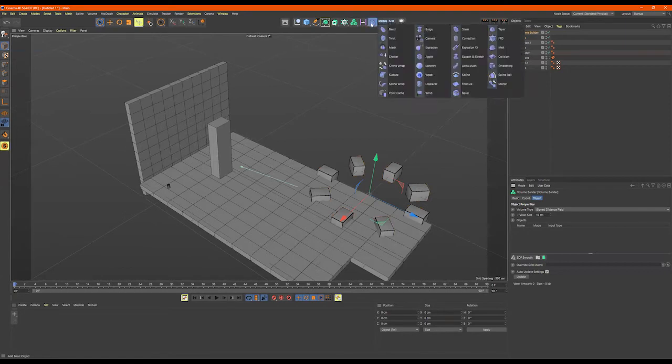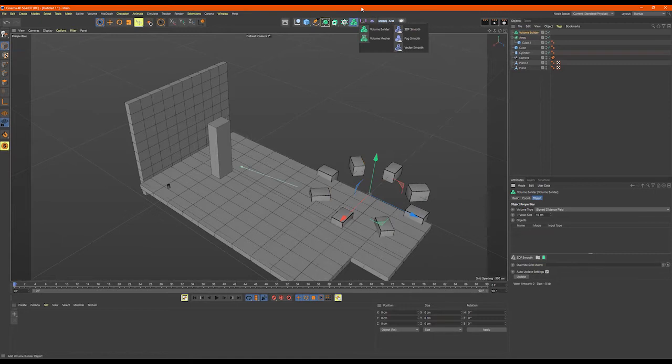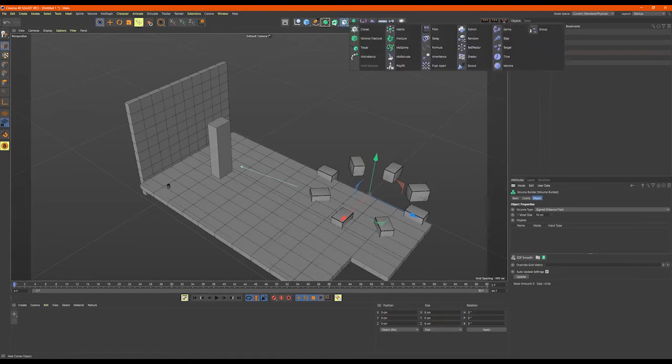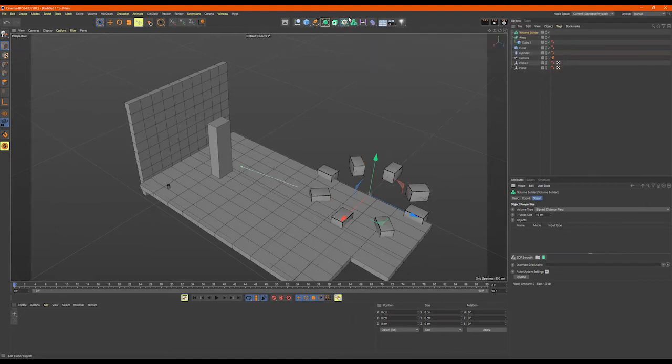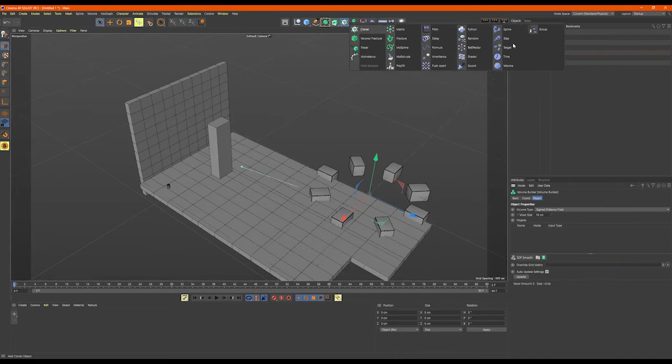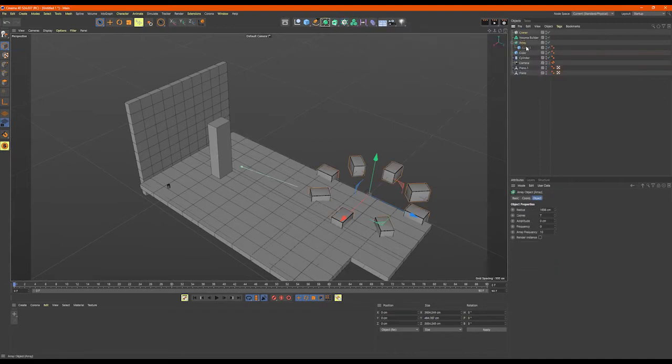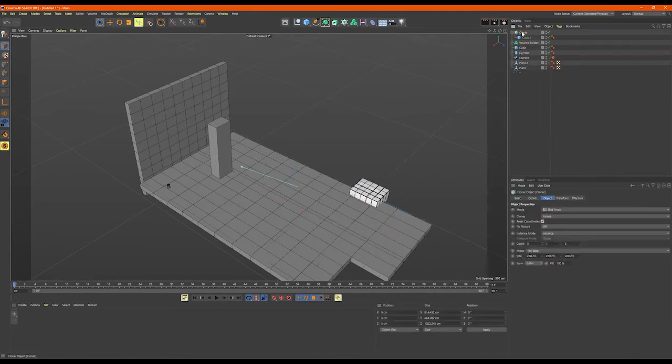No, it's actually not. No, my bad. It's cloner. That's what it was. Wrong tool. So cloner. So let me take this out of array. Don't need array. Gonna click and drag this into cloner. Delete array. Click on cloner.